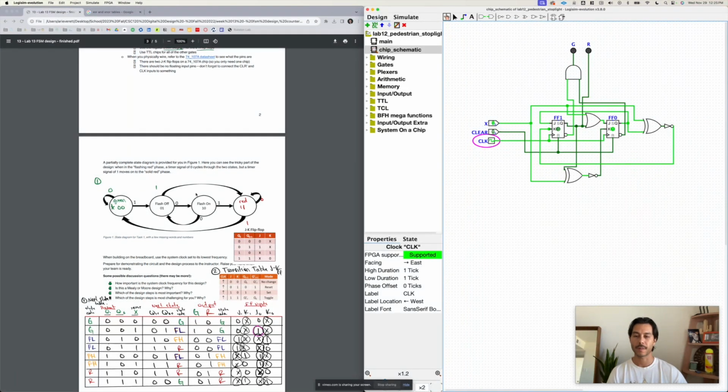Let's go into flashing on and off. So that's 0. We have to make sure that X input goes down to 0 and then run this twice, a full clock cycle. And we can see it's on here. And we can keep that input at 0 and flash between on and off. So either way, when we add a 1 at the flash on or flash off per the state diagram, it'll bring us to red. So timer as the X input, and we run that clock cycle, and we're into red.